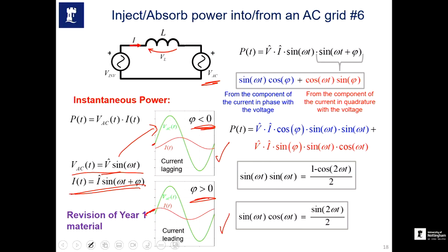If your load is inductive, which one of them is actually showing that characteristic? First one, yes, absolutely, because in an inductor, the current lags the voltage. So that's why the first one is what you'll see when the current is inductive, if you think of it as a load current.